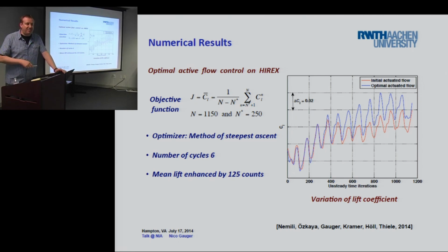It was kind of complex step, because we compare with the forward mode of automatic differentiation, which is equivalent to complex stepping. So we really can calculate the finite differences with step size 0, so to say. You know that finite difference is right, so that's how you compare the adjoint, and that's verification. Yes. So that's how we set up the adjoint always.